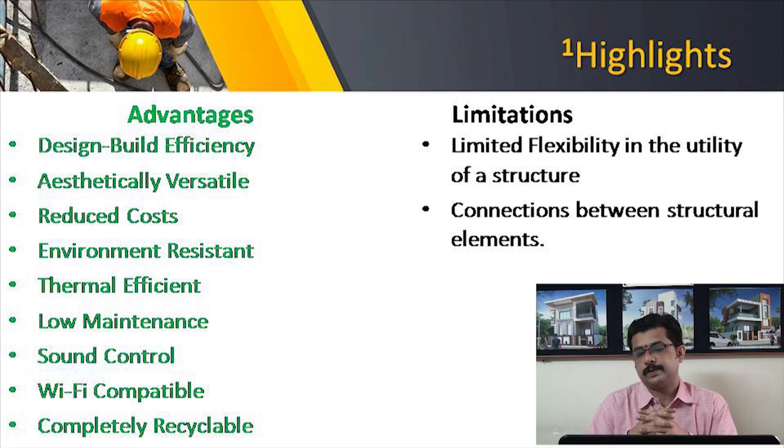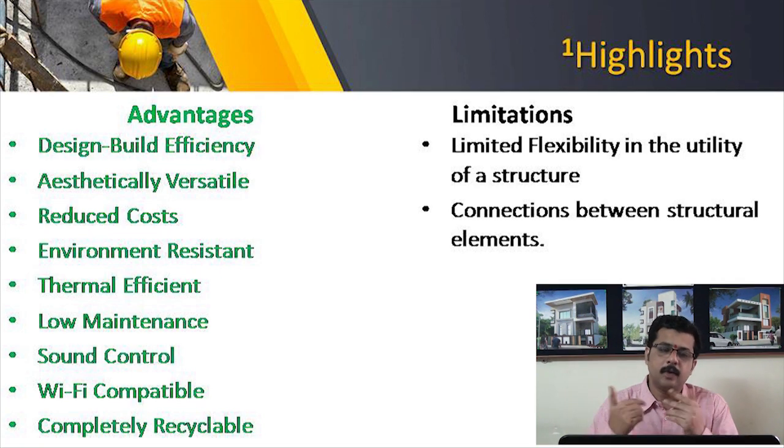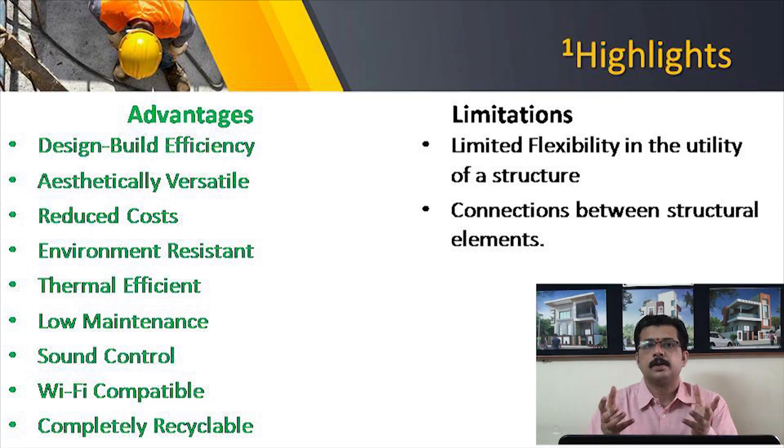It reduces cost. How? Precast concrete products are manufactured off-site under a roof, and they are transported to the site as and when required for installation. This compresses the project duration. This cuts short the requirement of labors at the site. At the same time, only few people and agencies are involved in the manufacturing of elements. This way, it reduces the overall cost of the project.